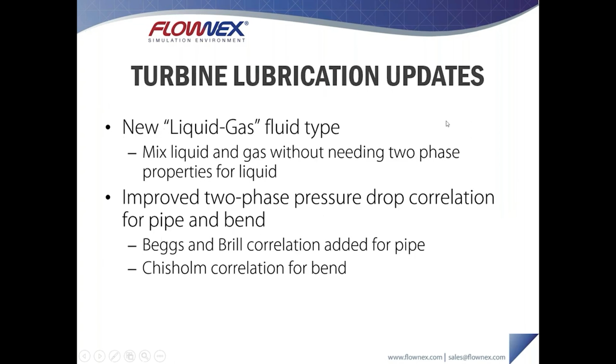Okay, so just to talk briefly about what the latest Flownex release this year included. There are a few other things outside of this, but these are the two main sections that are related to this webinar. The first of which is a new fluid type. It's a liquid gas fluid type. It basically allows us to mix an incompressible liquid with a compressible gas fluid, and we just specify them as a standard liquid fluid and as a standard gas fluid. There's no need for any complex fluid properties.